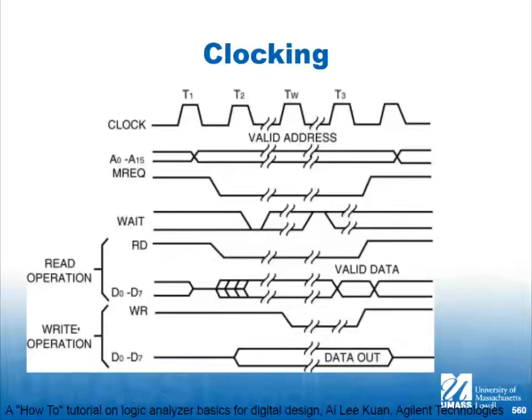So I can asynchronously sample and I don't have to worry about being efficient about the memory. And honestly, I use it for Raspberry Pi and Arduino projects where I'm looking at SPI buses and things like that. So it's not critical that I have a lot of memory. And it's only 16 channels, right? These larger logic analyzers have potentially hundreds of channels, and that uses up memory as well. But it's only 1 bit per sample as opposed to the oscilloscope.